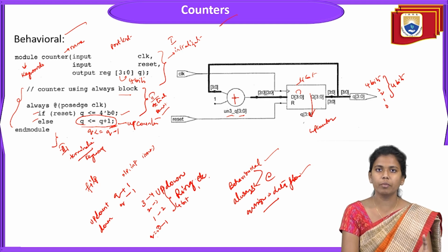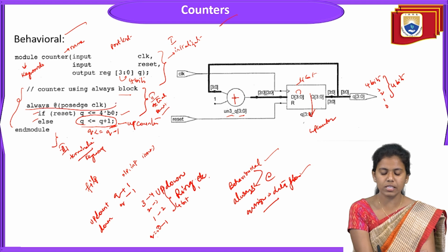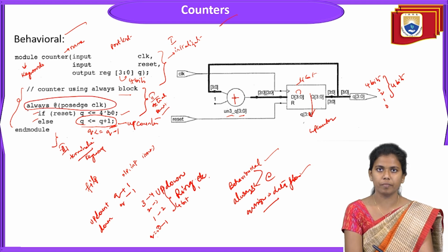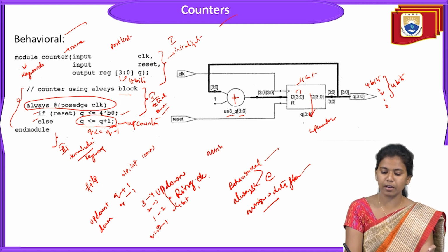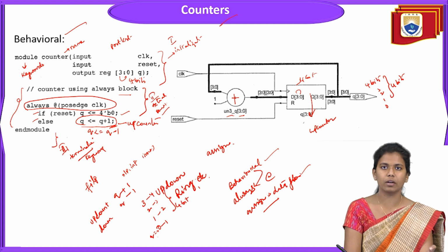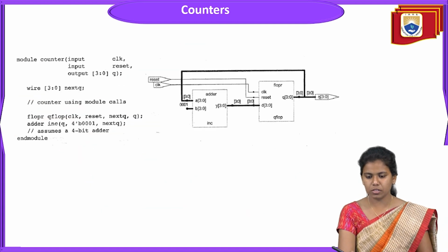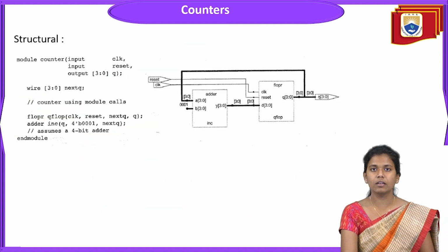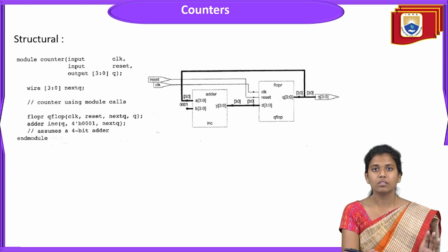Always remember, in behavioral modeling we will be using always @(posedge clock). If we are going for any data flow modeling, then always remember assign is a keyword. So this is about the counters. The previous topic was behavioral modeling, and now we will see structural modeling.